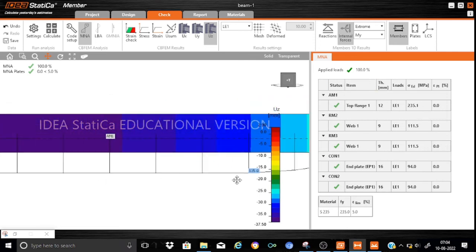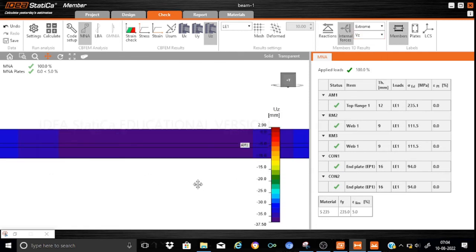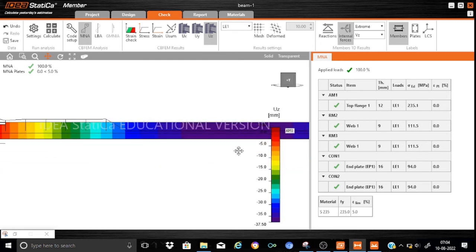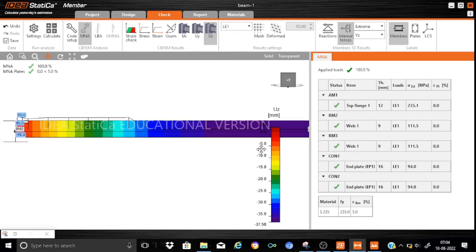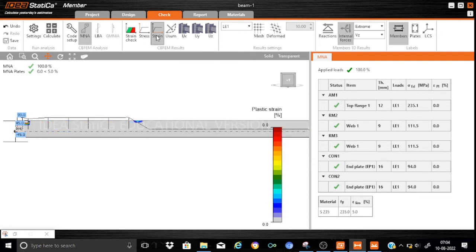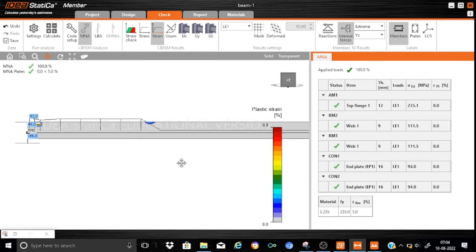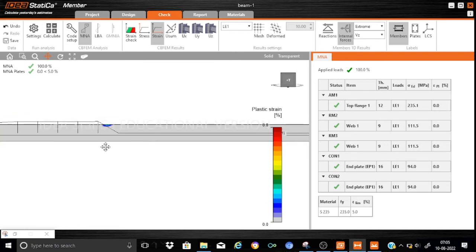Now, similar to the bending moment, you can also visualize the so-called shear force diagram. You can just press the VZ button, and the VZ button will provide you the shear force variation. So you can just see it here. So let me just keep it plain, without any other colors. Yes. So you can very well see that this is how it is subjected to a concentrated load. So obviously we know that it should be something like a triangle.